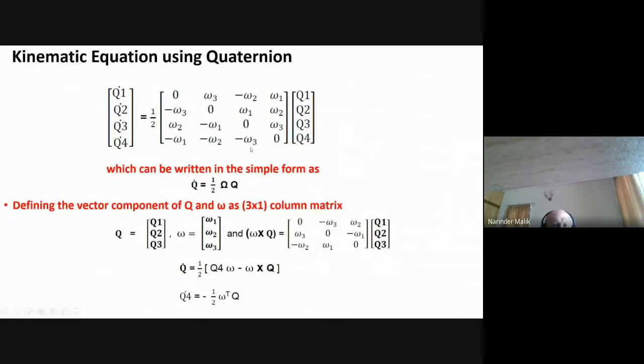Now this quaternion can be propagated using this value. So you can define your attitude in the quaternion form, and the spacecraft body is undergoing complex, simultaneous rotation about all three axes. By measuring the rate of the body axes using gyros, I can propagate the attitude with time. I can write this equation in this form, where this capital omega represents the skew symmetric matrix.